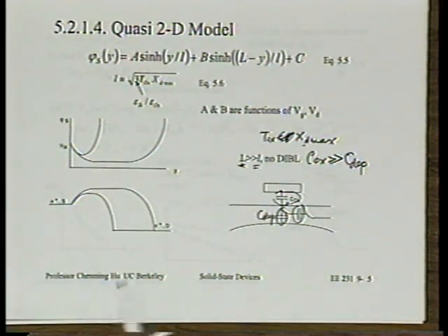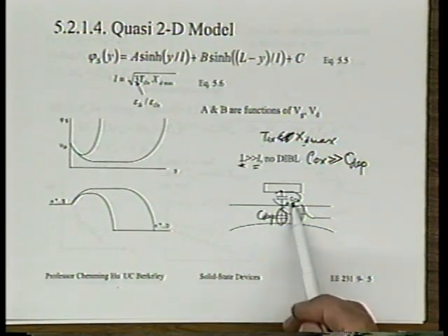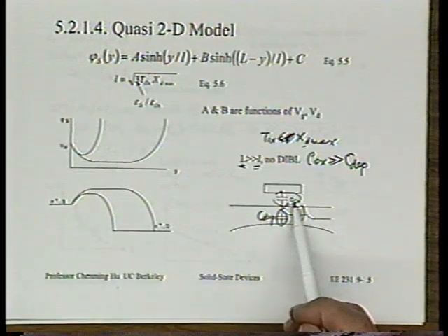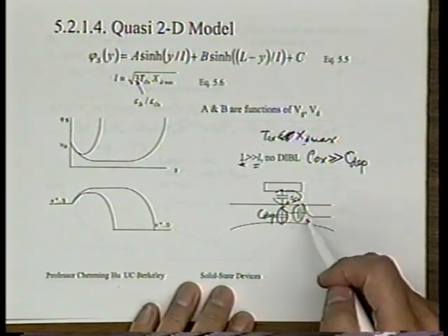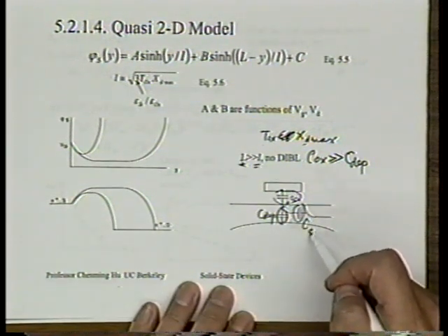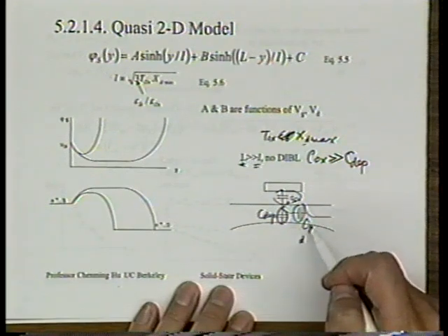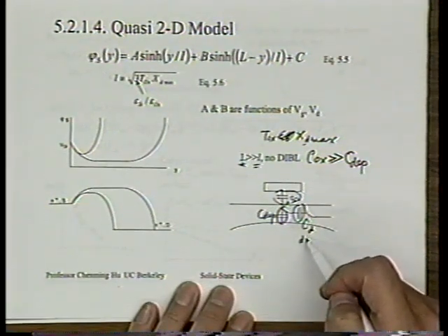Now that you know what we want in terms of length, I want you to restate it in terms of capacitance. Isn't that what we want? We want the gate oxide capacitance to be large. We want the backgate capacitance to be large. And I'll introduce a new terminology here, CD, called the drain capacitance, the drain-to-channel capacitance, to be small.